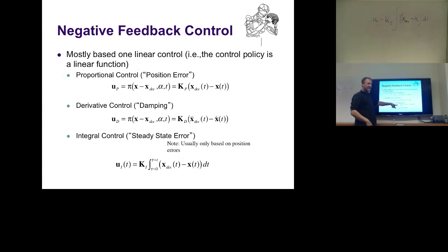But if you have an integral term, you fall down, but now you have an error left. This error now starts to get summed up. You take this error, multiply it with k, and create a motor command. It will get you a little bit up, and you get up, up, up until you finally reach the goal. Again, we'll see this in an example in a moment.